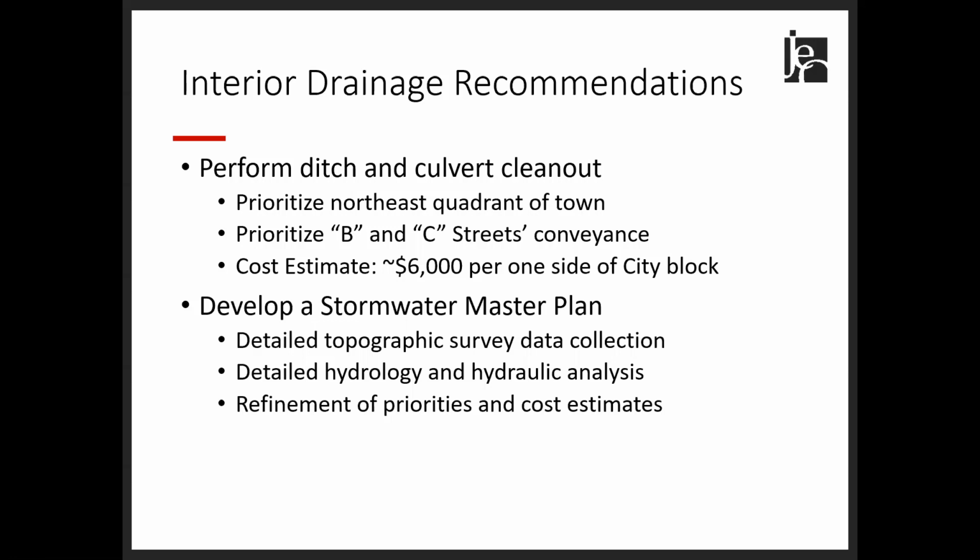The next step of the interior drainage recommendations would be to develop a stormwater master plan. That would provide more detailed survey data collection to allow for more detailed hydrology and hydraulic analysis, which would therefore provide for refinement of project priorities and cost estimates. So with the stormwater master plan, the town of North Loop would be able to know exactly which streets to work on first.